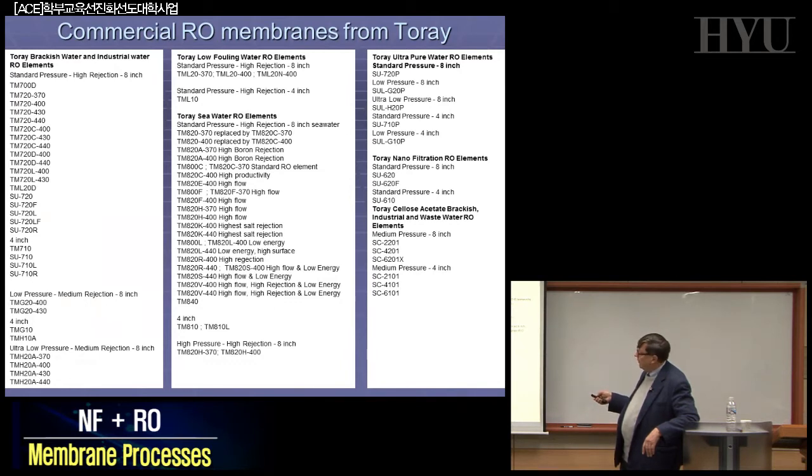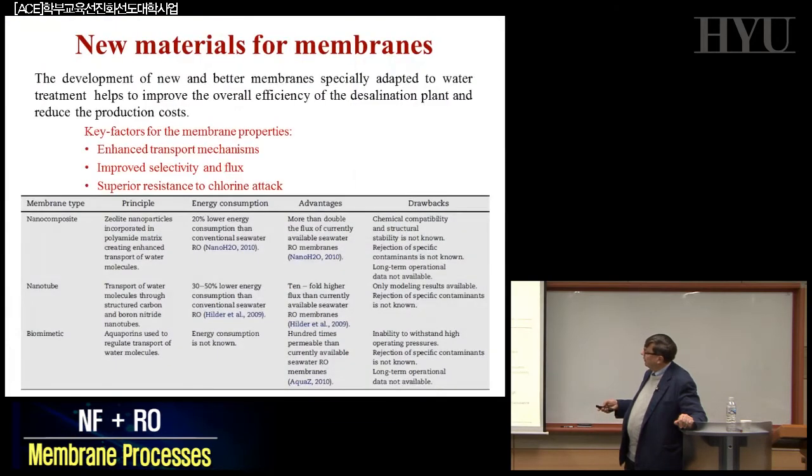Boron is a big problem because if you concentrate boron during desalination, this boron then goes again into agriculture, creating trouble. So you have to find membranes with very high selectivity for boron, and a specific membrane having this kind of property. And we know about boron, but tomorrow it will be the same for some other metal that we still don't know about, what happens in 50 or 100 years of using water with a concentration different from the traditional one. But the boron case is very well known, and membranes have been designed just for boron.